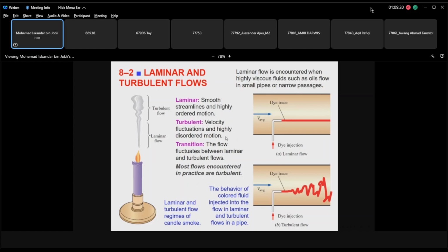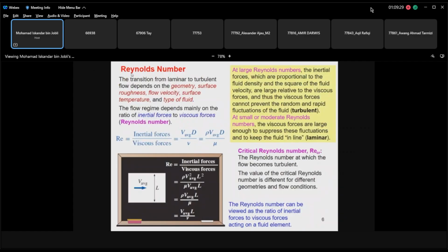So that's what it is, right? If you need to know whether the flow is laminar, turbulent, or transition, you can get that information from Reynolds number. And how would you determine the Reynolds number? By using this equation. Simple, right? You can read all this stuff, but it's actually just this: Reynolds number equals this. Mark my word, this is the only thing that you need from this slide. Reynolds number equals rho V D over mu. Or we can write it as V D over nu here, because mu over rho is equal to nu. It is simple.